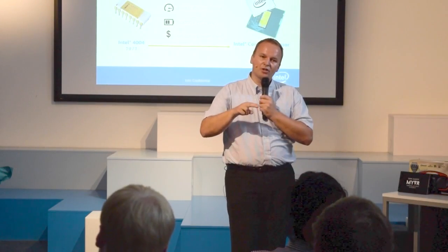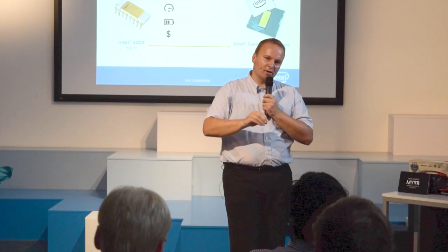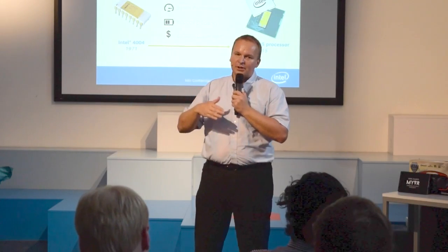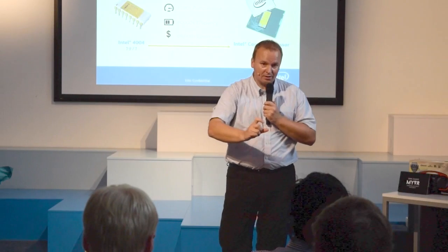That is a very good question, but it's also very difficult to answer, because really what those numbers mean, they're technology nodes. The memory manufacturers actually had a formula on how they derived their technology node from the actual structures that they produce. For processor manufacturing, it's a little bit different. The really significant parts of a transistor, for example gate length, are significantly smaller than the technology node you're on. So if we used gate length, we would actually have much smaller nanometers today.